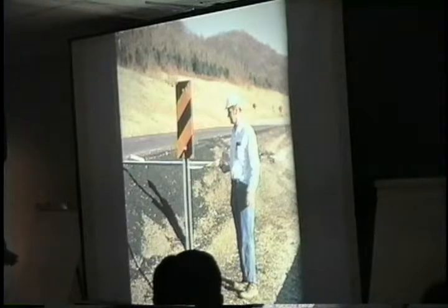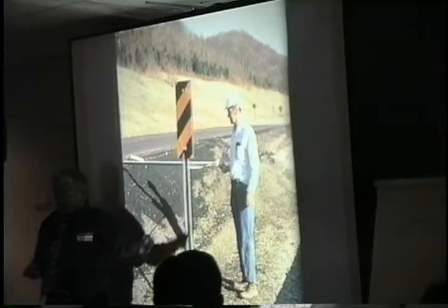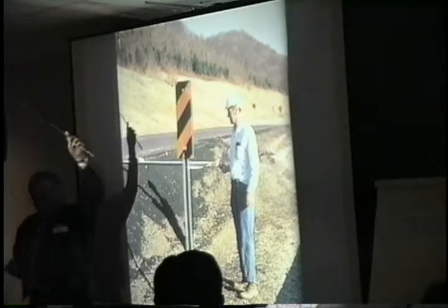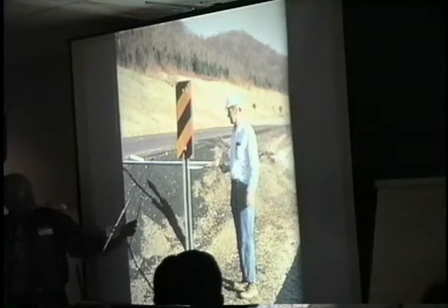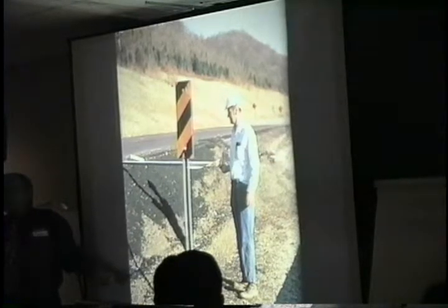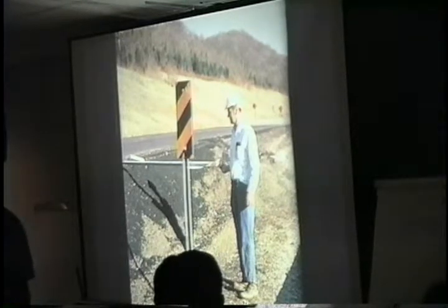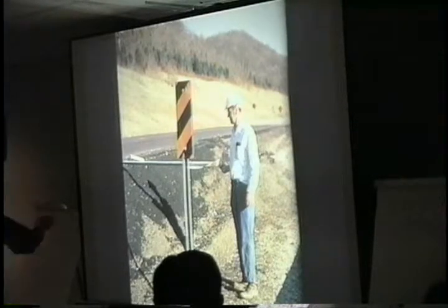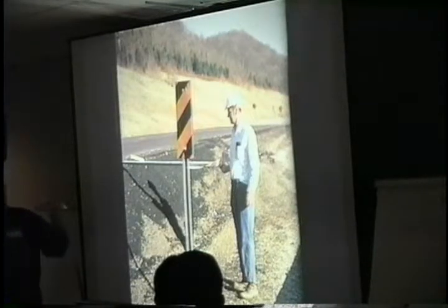And this is the geotech engineer from your neighboring state here in Kentucky, Henry. This guy is about 6'6", I think he is, and he's measuring almost 5 feet of asphalt material that has been placed here by maintenance on this landslide that has been creeping for years. Maintenance has been coming up and overlaying and overlaying and overlaying to where they have 5 feet. Luckily, maintenance went up and reported this to the geotech people, and they went out there and designed a correction method before the whole thing failed.